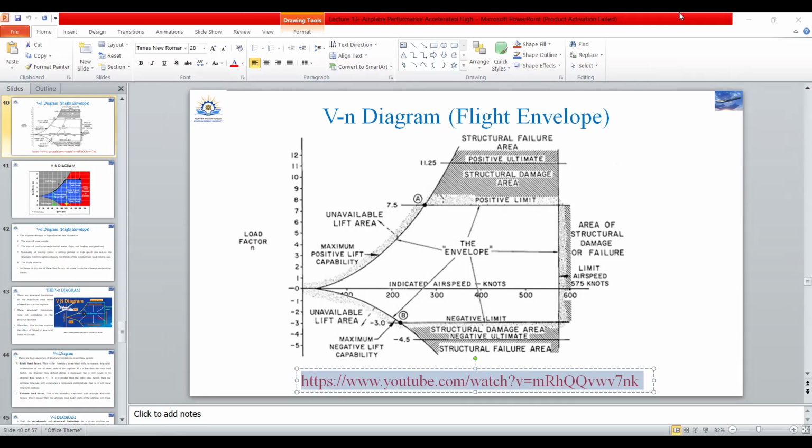What is a VN diagram? A VN diagram is a graph between velocity and load factor. This graph has velocity on the horizontal axis and load factor on the vertical axis, and gives details about an aircraft's operating strength. Each aircraft has its own VN diagram for a certain weight, configuration, and altitude. Weight, configuration, and altitude are important parameters. What is load factor? Load factor can be defined as the ratio of lift to the weight of an aircraft.